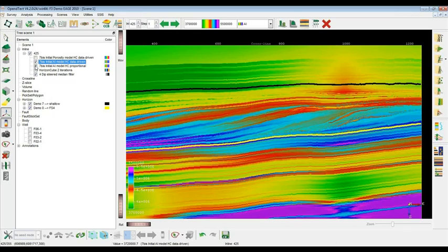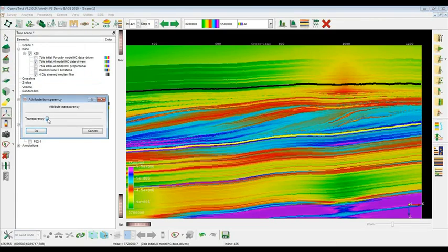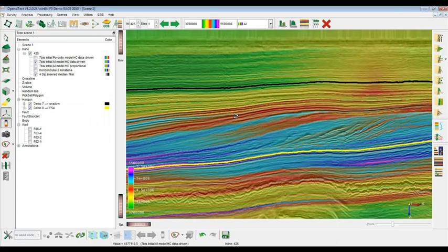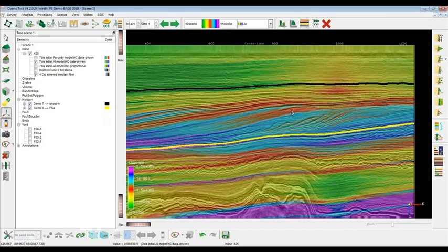This will become more obvious if I show at the same time the gridded outputs with some partial transparency on top of the seismic data. Now you can see much better how these impedance layers in the initial model actually are following the seismic reflectivity. And that is the whole purpose of this exercise. It is the whole purpose of including a HorizonCube as an input to the gridding of the well logs.